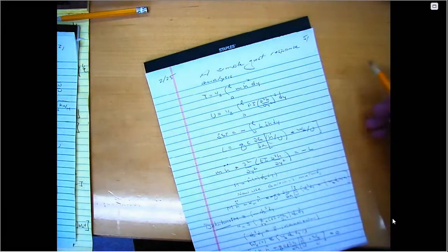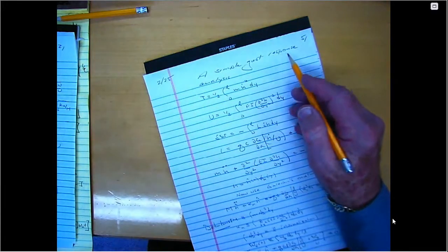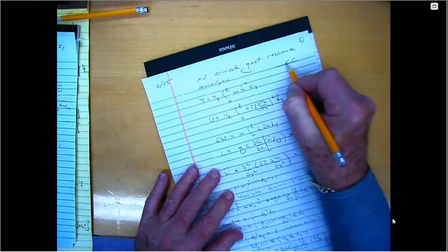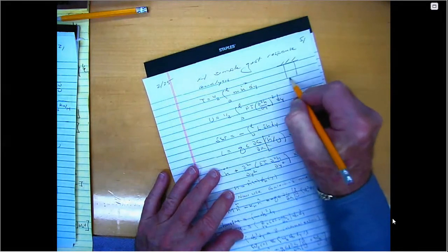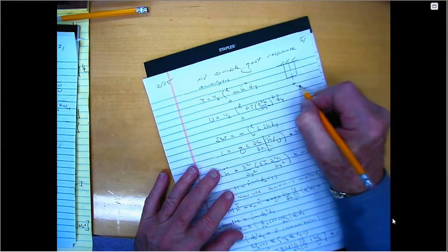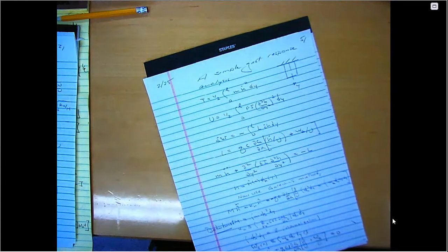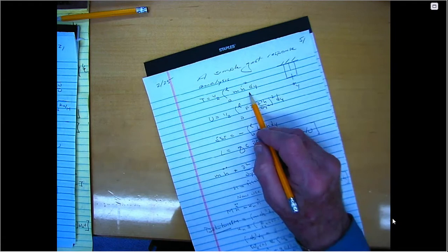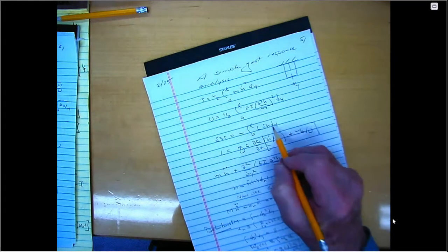So what we're going to do is a simple gust response analysis. And what we're thinking of is a wing like this with an elastic axis. Whereas in reversal we concentrated on rotation, it turns out that for gust response, the main response of the airplane is usually in bending. And so often people just include the first bending mode of the wing. So we're going to do one bending mode of the wing. There's dynamics, so we have kinetic energy as well as potential energy as well as virtual work.